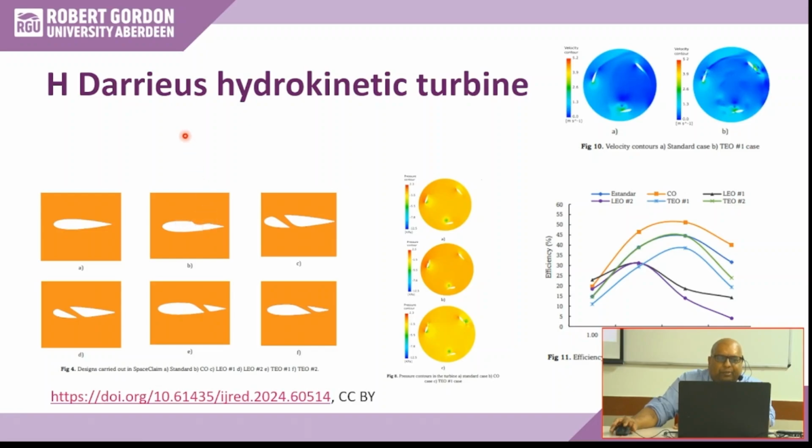If you think about a golf ball, has anybody seen a golf ball? A golf ball has a lot of dimples. Why are there dimples? To enhance turbulence and to reduce drag force basically. Minimize the flow separation or trigger the turbulence, so that what we call a drag crisis happens at a low velocity. So think about that one. We have dimples on a golf ball, so why don't we put some dimples here and see if you can have reduced flow separation that your friend was talking about.